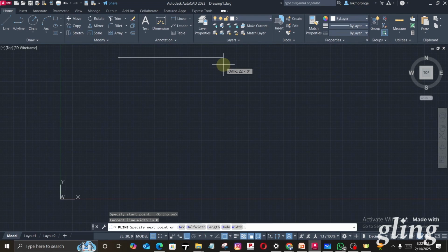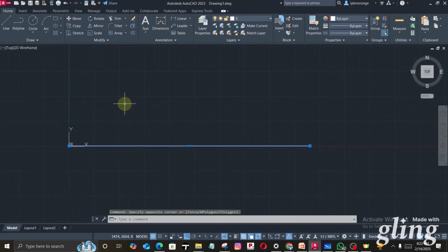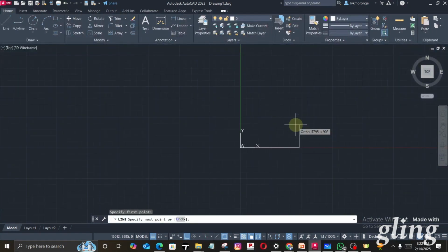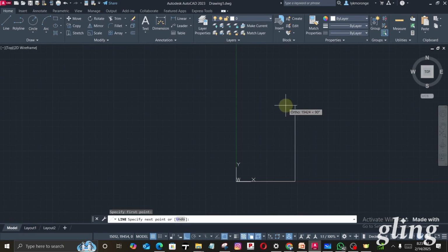We had set our units in millimeters, so we want to draw 15 meters. That will be 15,000 millimeters, then click OK. Then zoom, and go back to your command line. This makes sure that you are drawing proportional objects. So that is 15 meters horizontal distance by 30 meters. This is not the exterior wall, this is the site plan.